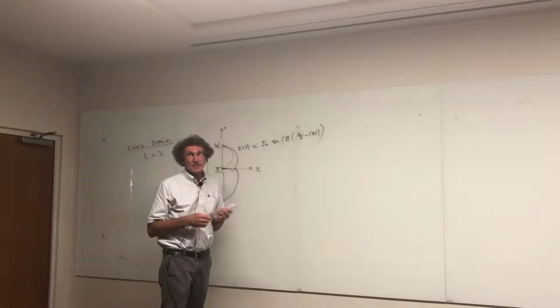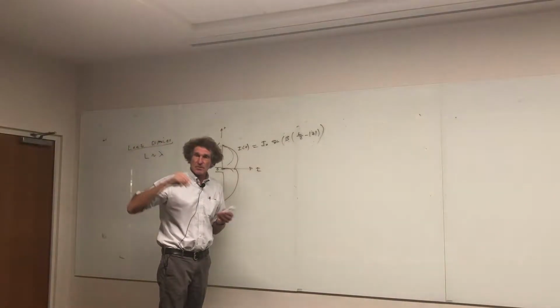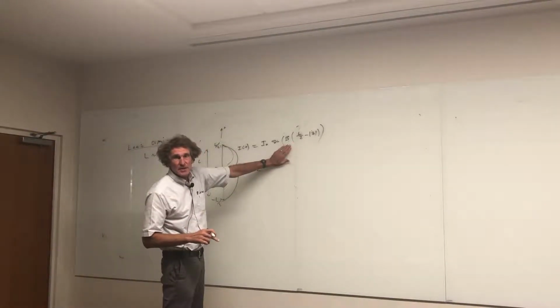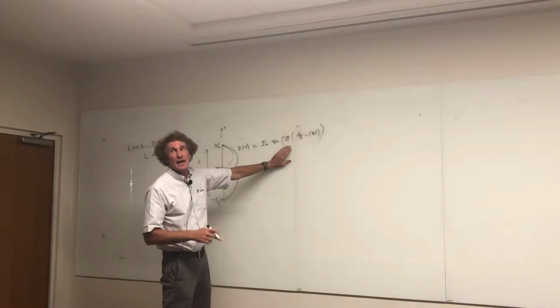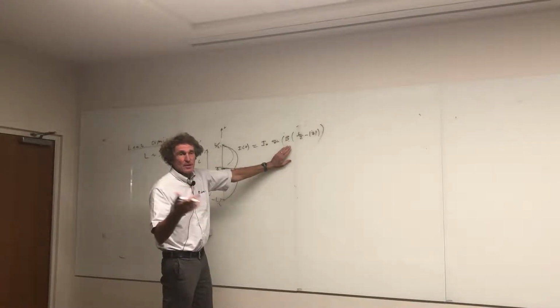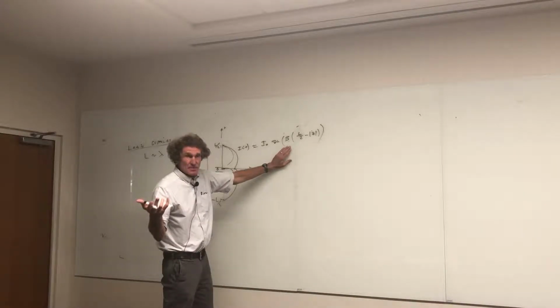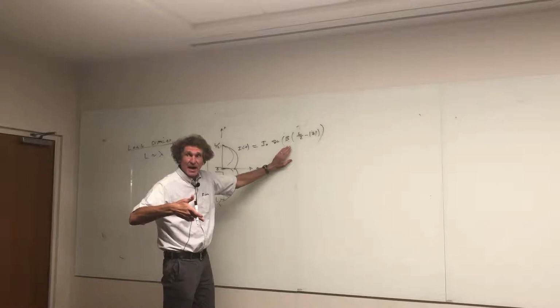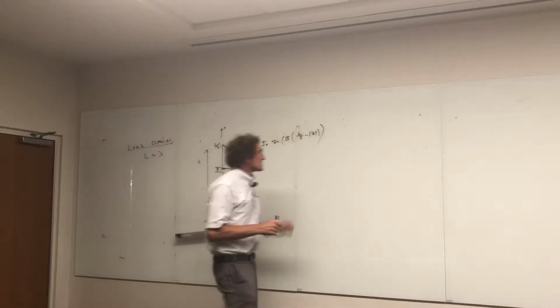for any voltage, it sounds like nothing's being radiated, but in fact it is, because it never goes to an absolute zero. Keep in mind, this is an approximation, to a high degree of accuracy. It will feed current in there. The impedance is so high that you're going to get a huge amount of radiated power, because the power is I squared times the impedance. Well, you can have a very small amount of I, but a huge impedance, and you radiate a lot of power. All right? Something to think about.